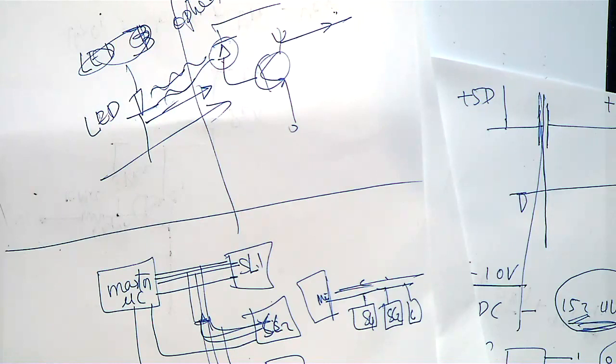Because these are some fundamental things people might ask you. Why do you need an address for I2C? Why is address clash happening? So that's the reason when you are interfacing 10 sensors, each sensor should have a different address. If you don't have different addresses, what will you do? You have to use a mux. Using a mux, you can select one by one quickly.